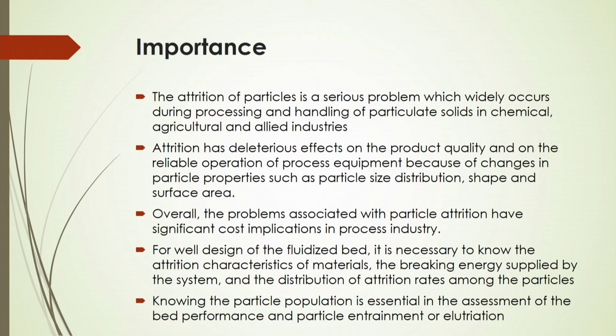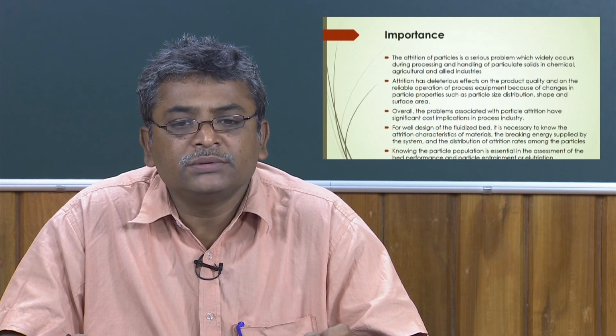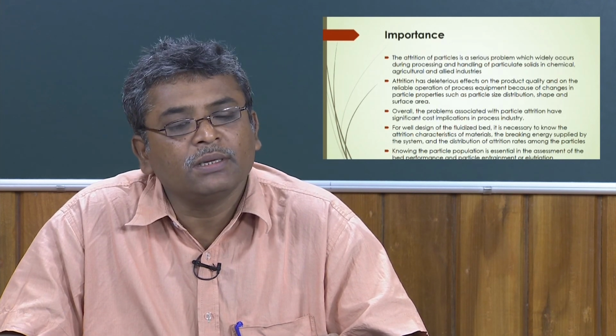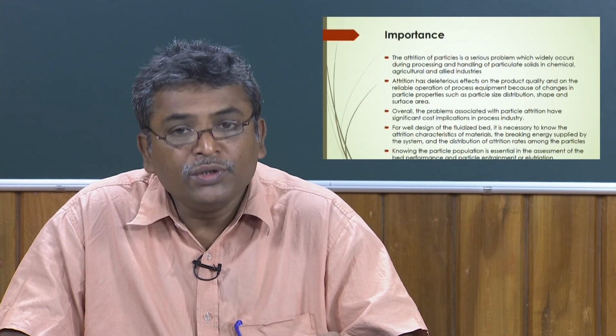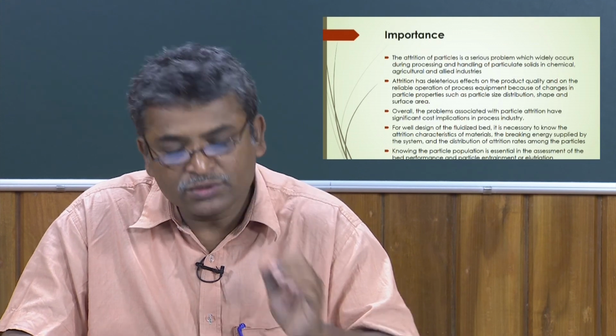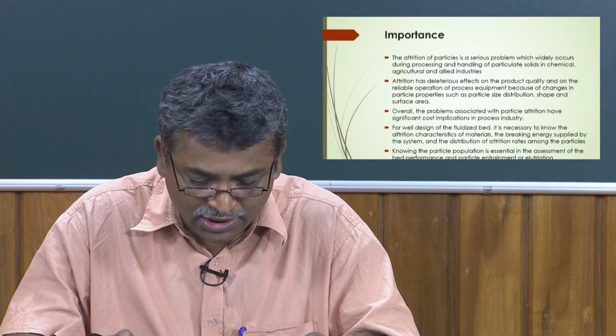For well design of the fluidized bed, it is necessary to know the attrition characteristics of materials and the breaking energy supplied by the system. You also have to know the distribution of the attrition rates among the particles before designing the fluidized bed. Knowing the particle population is also essential in judging the bed performance and the particle entrainment or elutriation inside the bed.